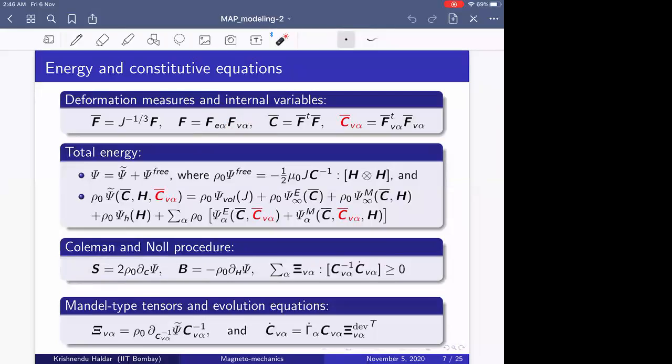So basically, in the continuum scale, if you think about Maxwell elements in a spring dashpot system, it could be shown that in a continuum setup, it can nicely fit this multiplicative decomposition. So this is your spring and this is your dashpot system, and alpha is the number of Maxwell elements you want to consider. So this is again a standard practice, nothing new here.